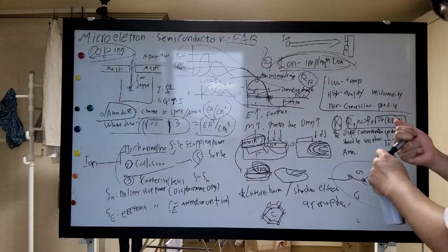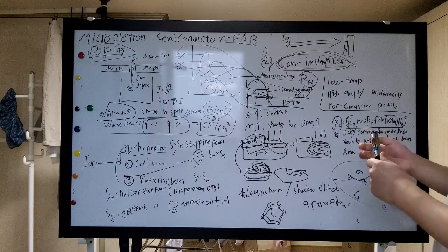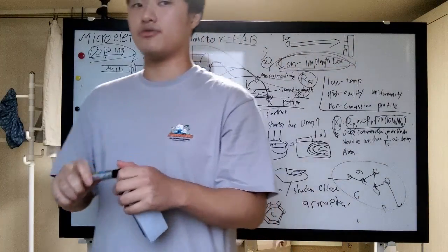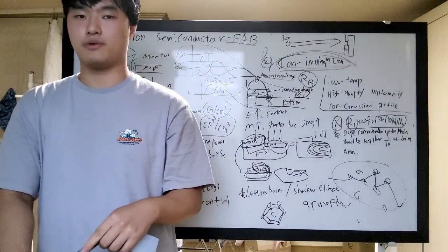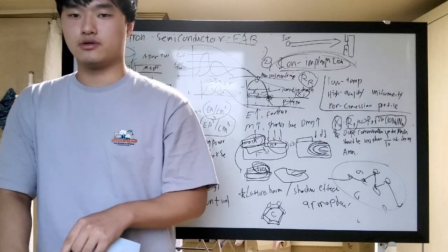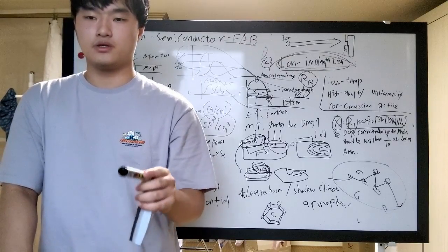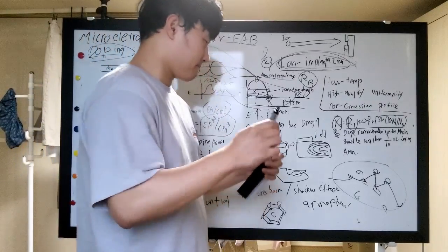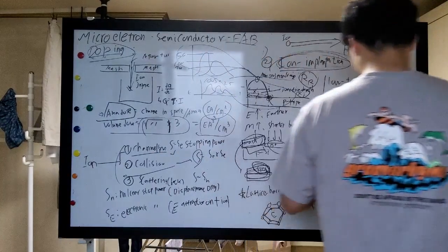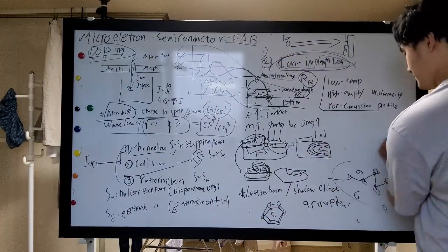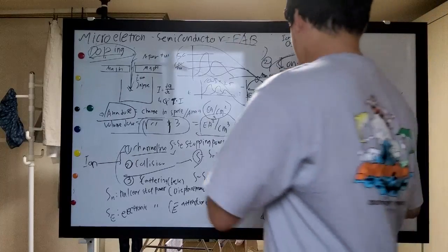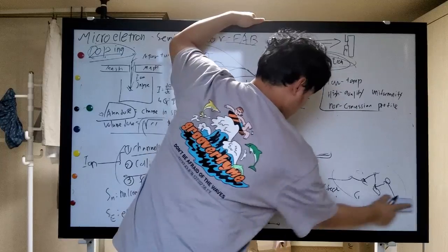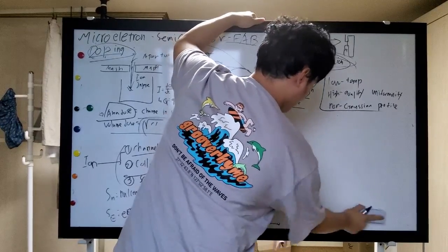So we say it is possible that the area underneath should not be doped beyond one tenth of the level of the silicon that is intended to be doped. And finally, the effect of lattice damage is something we want to talk about.